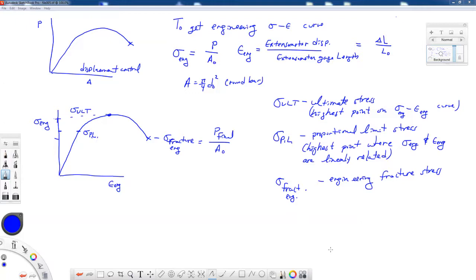Now, different materials have different stress strain curves. A low carbon steel stress strain curve has an upper and lower yield point. So these are some common features, but you may see some unusual things. And some materials have what's called serrated flow, and so things aren't very smooth. But again, this is just a pictogram to describe a generic behavior of a material.